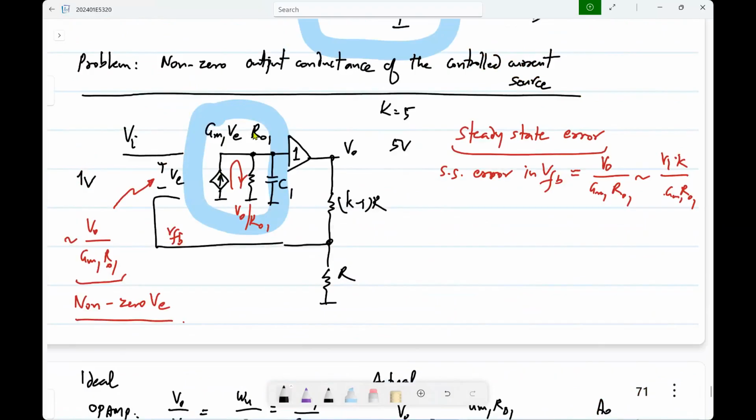Yeah, so that is one of the possibilities. You have a current controlled current source or a common gate amplifier. So essentially it gives you the same output current as the input current, but its output resistance is much higher. So that is definitely one possibility. Okay. So we will look at that. That gives you like a class of op amps. And then there are other things as well that we can do.